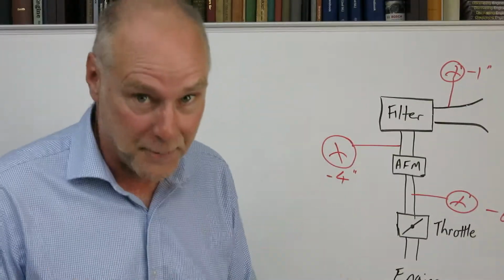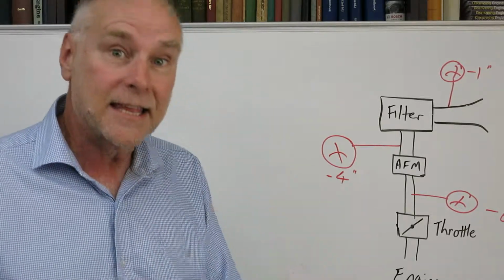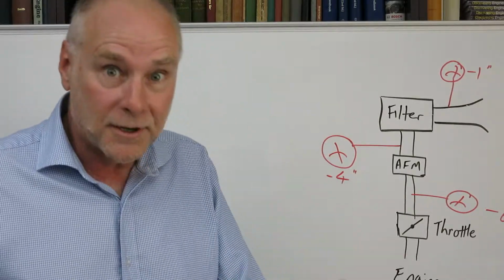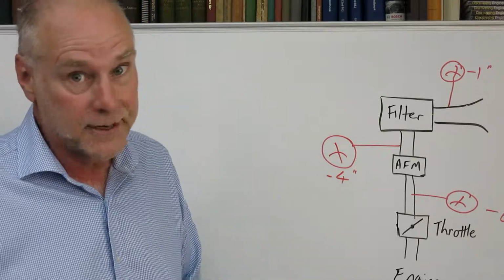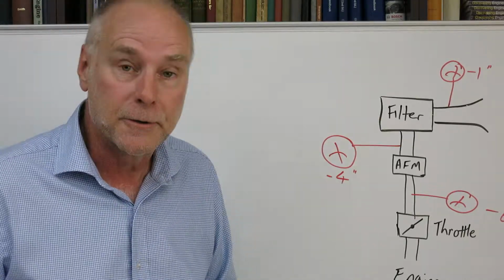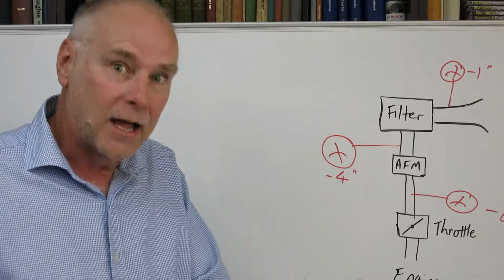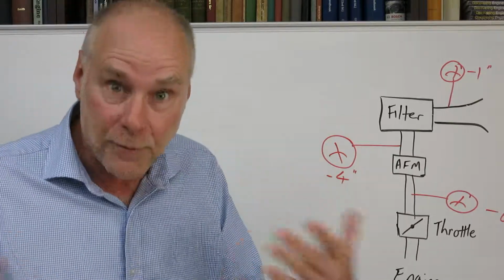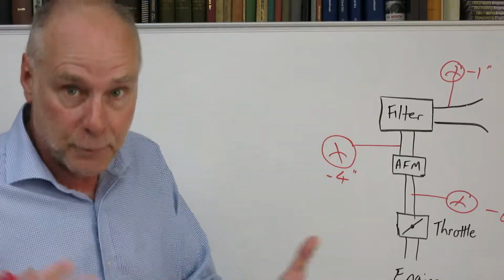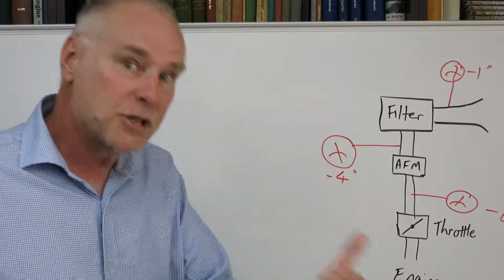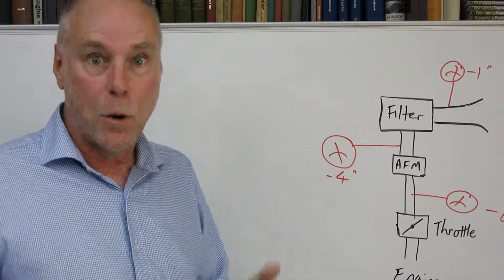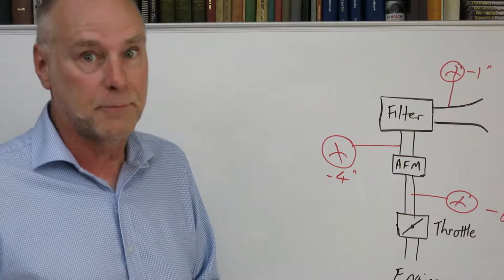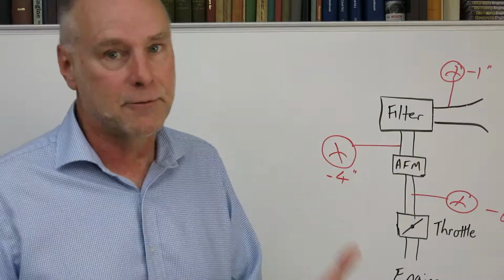Now, that's actually a fabulous intake system. Anything that's better, that's a smaller number than minus 10 inches of water is typically very, very good. And in fact, it's very hard to improve. But when you measure the total pressure drop, and always at full throttle, full power, that's where you'll get your maximum. When you measure that maximum pressure drop, on some cars, it's 20 or 30 inches of water pressure drop. And that's a severe restriction.